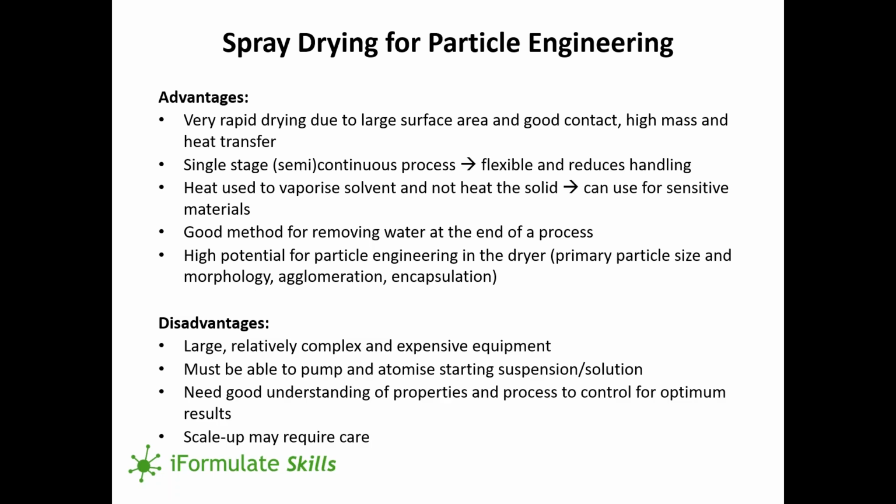Disadvantages: well, the equipment can be large and complex and expensive. You must be able to pump and atomize that starting suspension, solution, or emulsion. So there's got to be a pumpable feed to start with. And as we've seen, you need to understand the properties of your formulation and your material, as well as your process conditions, to control that properly for optimum results. And for that reason, also, the scale-up may require some care.